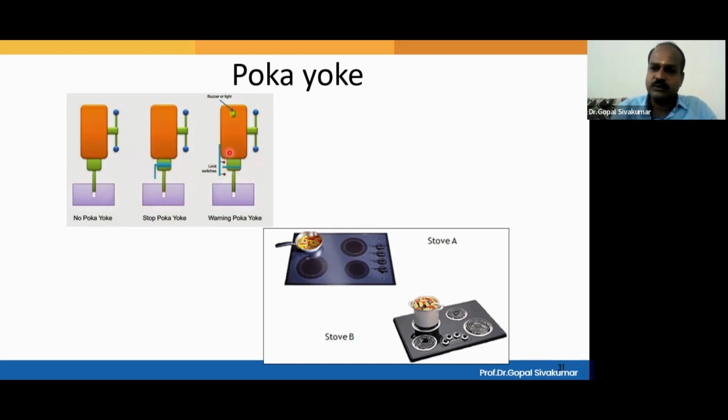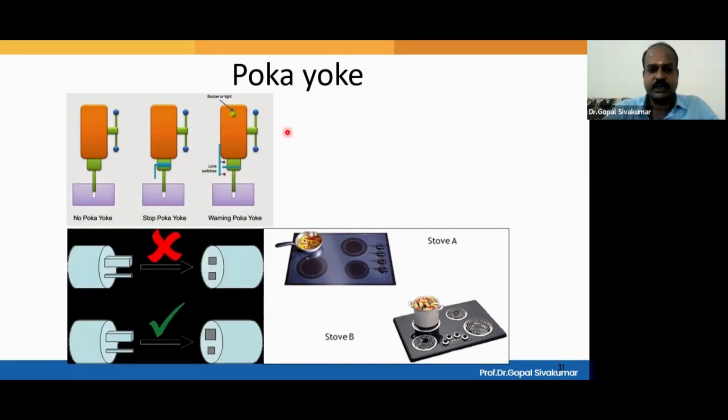Similarly, you can always think of going one step ahead. Here, in addition to the stopper, a buzzer is also added. So whenever the stopper hits and the drill bit continues to run, then immediately the buzzer will also give a kind of sound or a light, and so the problem will immediately come to the surface, and then some control measures can be taken.